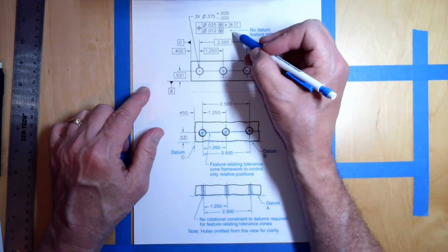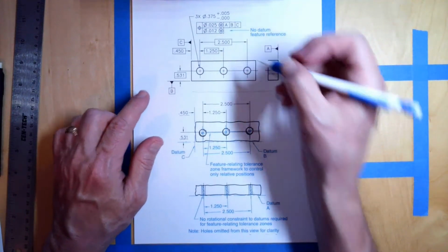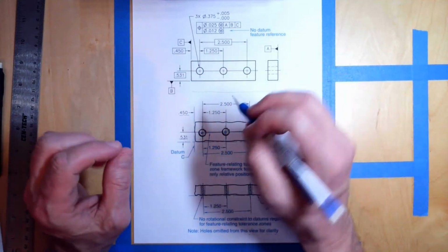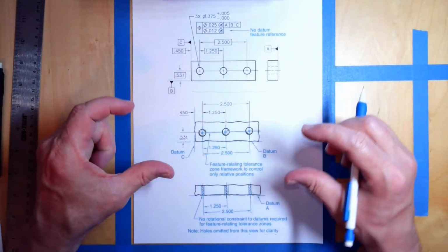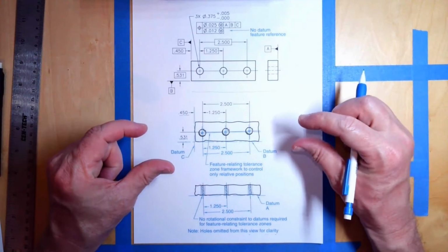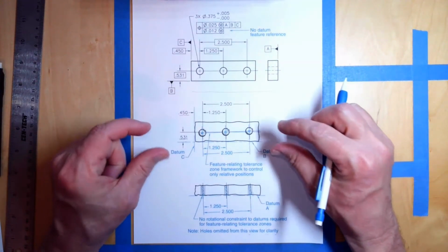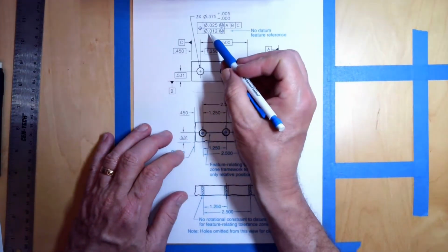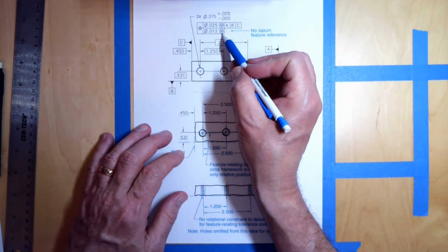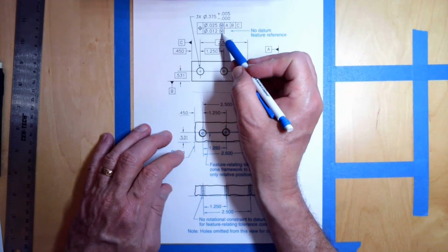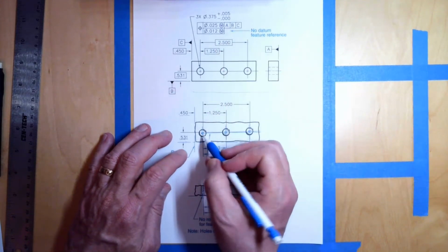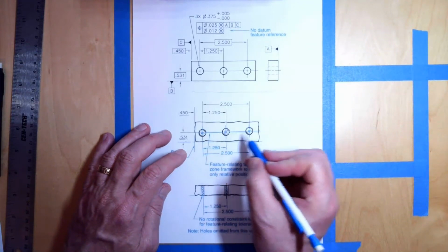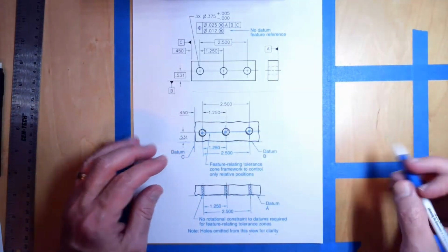Now, because we have no repeated datums here, then what that means is the flats, the feature locating tolerance zone, is unconstrained and free to rotate and translate within the pattern locating tolerance zone. Okay, so this O12 at MMC, 0.012 tolerance zone at MMC, which is the smaller tolerance zone right in there,